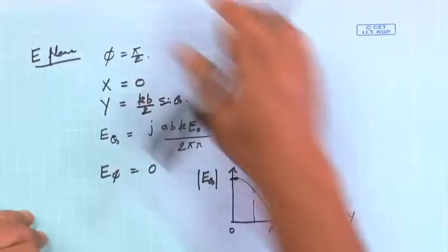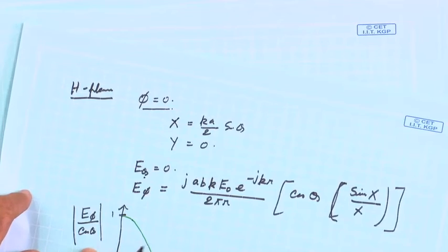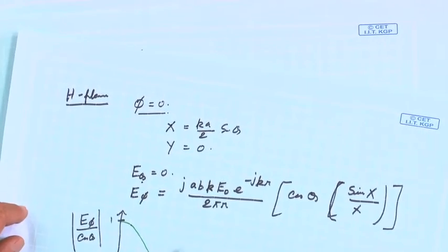But actually the two patterns we have drawn, E plane is this, and for H plane pattern, here we have made a cos theta thing. So, that cos theta if you bring, then this will not be simply that A and B replacement. So, away from both side, cos theta term also needs to be incorporated.